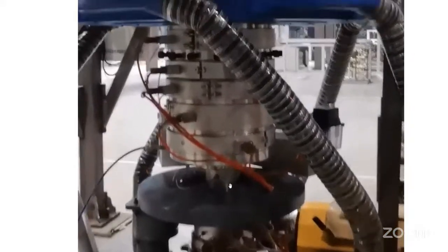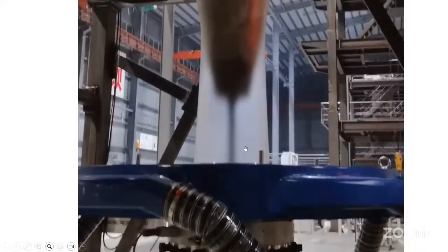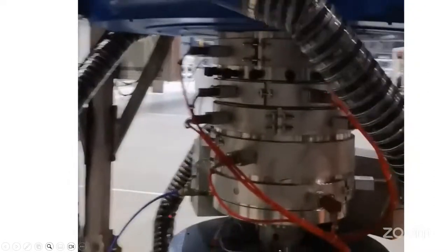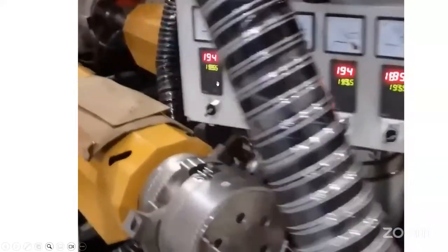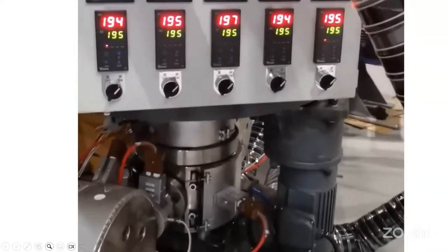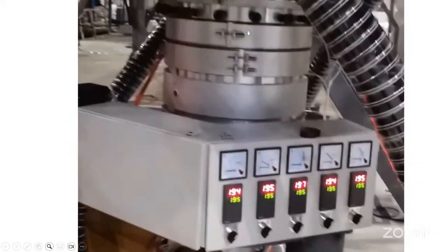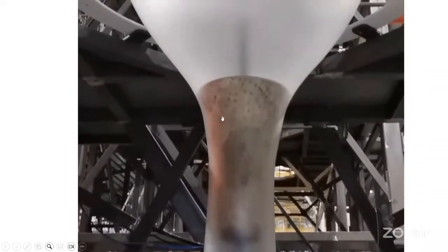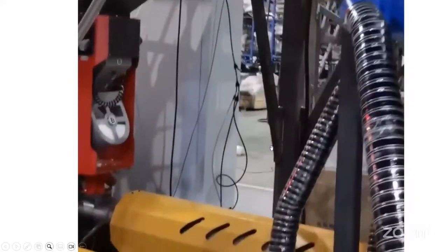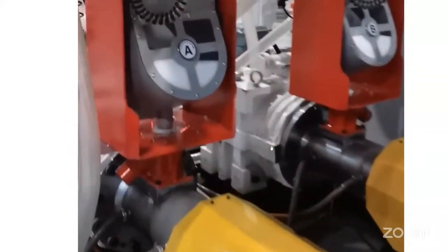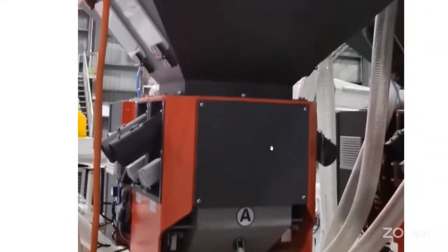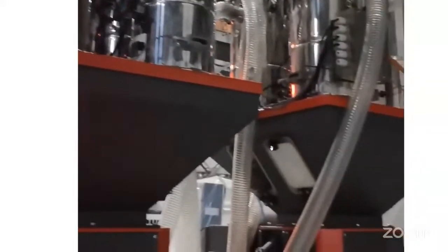See here. There's a die here, friend. See here, the die is here. And see the bubble here. Here the cooling takes place inside. There is co-extrusion. There are multiple dies here. And see here, a spiral die. And this is a bubble now. See how this is on a mandrel, friend, which will give the cooling effect to the bubble. This is a very sophisticated plant here, friend. It's called co-extrusion.